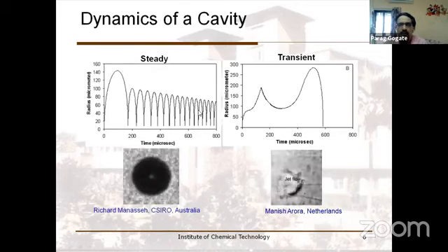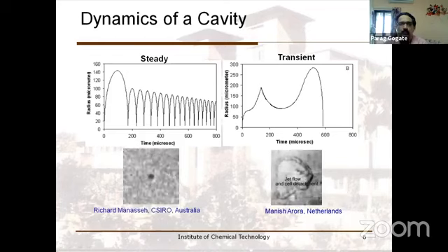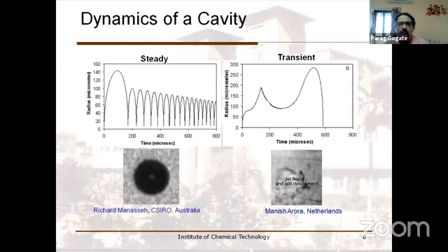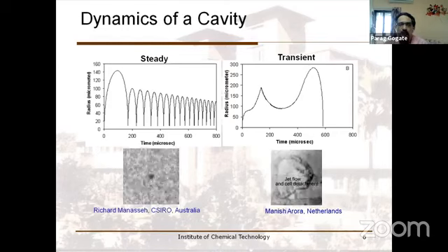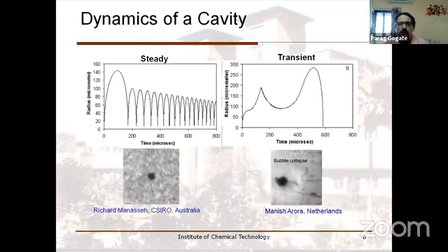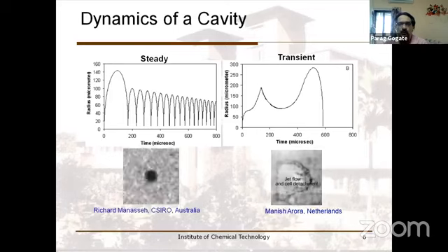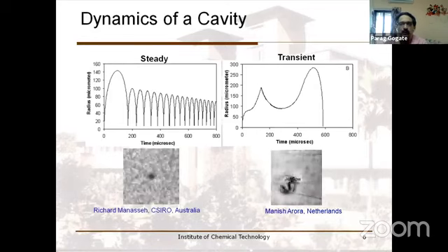Now, as I said, the cavitational intensity is going to be different. And also the energy requirement to generate these cavitation is also going to be different. So you need to match the requirement with the desired energy consumption, because finally, depending on the application, your cost of treatment is going to be extremely important. So I don't want to spend too much energy if it is not required.